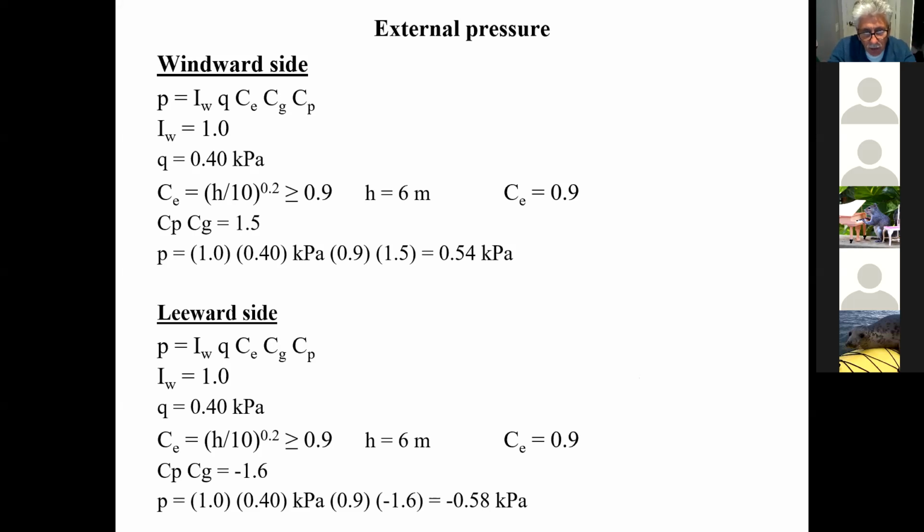As far as which side it is, it makes no difference. As a matter of fact, the wind can be blowing from the other side all of a sudden, you understand? So we don't worry about which side we're designing for. We're going to try to find, let's call it, the highest pressure. And once we find the highest pressure, we'll design them all for that pressure. This way, no matter which direction the wind is blowing, we know we've got it all covered.